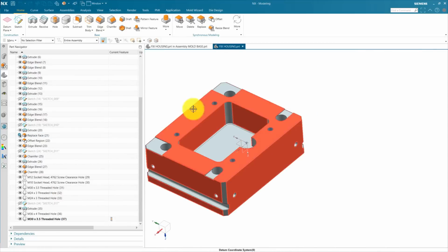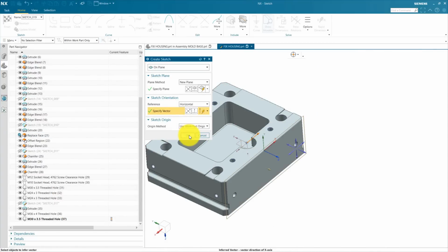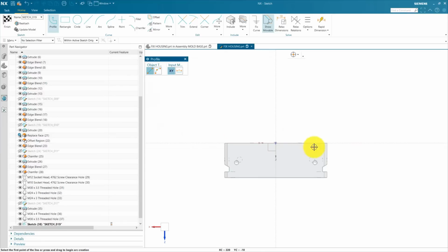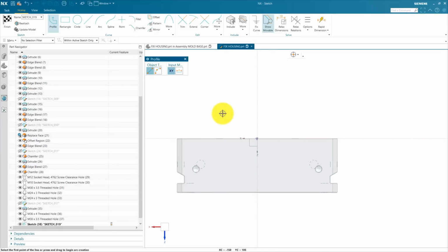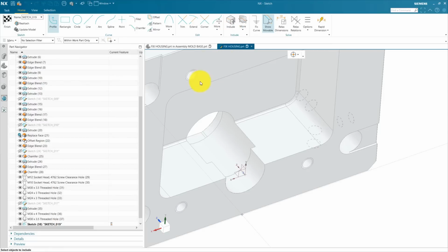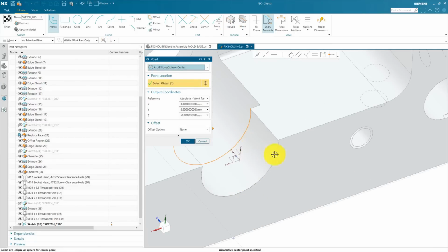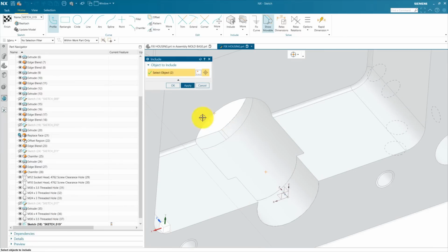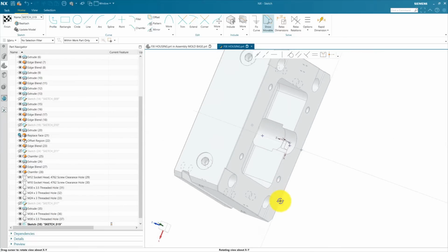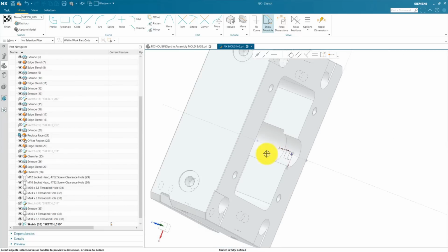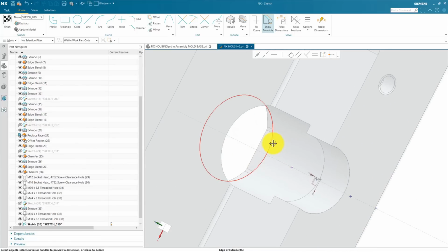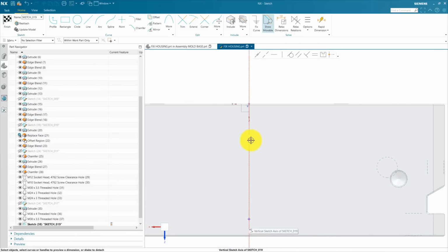Now we are going to add a cooling line for our Sprue Bush. It must be there. The dimension we will change after we analyze our Sprue Bush design. We are going to include, and maybe we can include some points from here. Yes, here we created 2 points, one from this face level and one from this face level. This is the length of the ring.